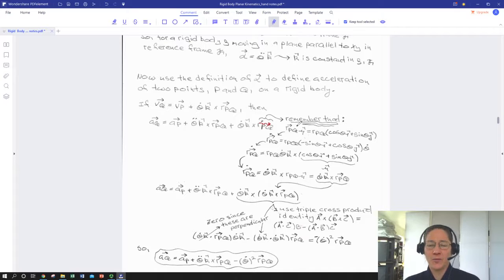So we start by saying we can express the vector P to Q as, good heavens, we have arrows in the wrong places, as the magnitude, the length of the line from P to Q, times a unit vector that denotes its direction. This is the unit vector U. And this was the one that we used to define the angle theta of the body's rotational angle versus the reference frame. That was what was moving and ended up defining our rotational position, velocity, and acceleration.